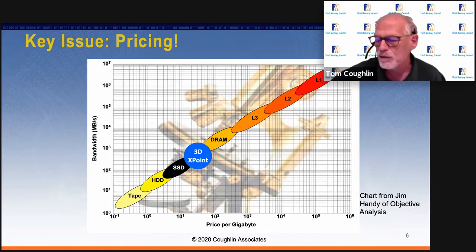Although Intel probably lost well over $1 billion per year on Optane 3D Crosspoint while they ramped it up over the past 3 years, as of the last quarter, it reported no losses, probably because it started to reach production volume that lowered the cost below the price it must sell for. Intel had to overcome a chicken and the egg problem. 3D Crosspoint must be cheap to sell in volume, but 3D Crosspoint must sell in volume to get cheap. The same problem stands in the way of other emerging memories. NOR's hard stop at 28 nanometers and the size of SRAM opens the door for other technologies to take over as the embedded non-volatile memory in systems on chips. Today, MRAM is a leading candidate in this race.